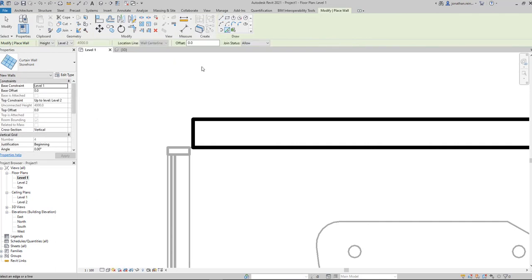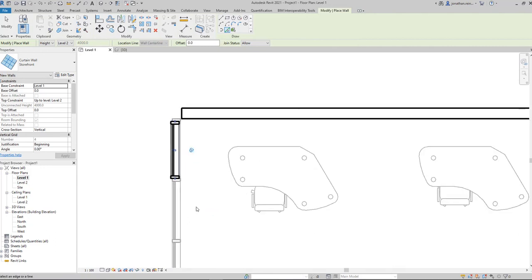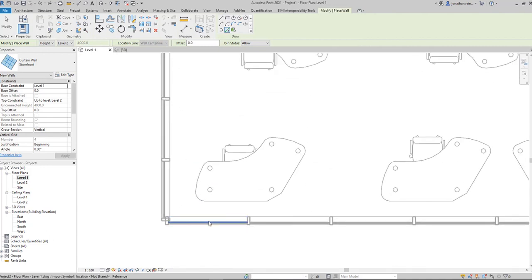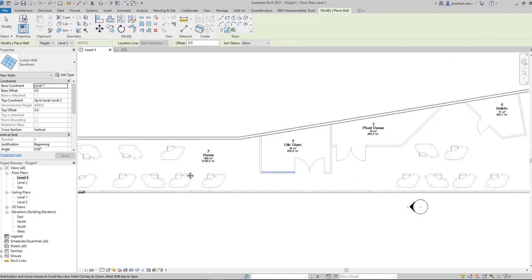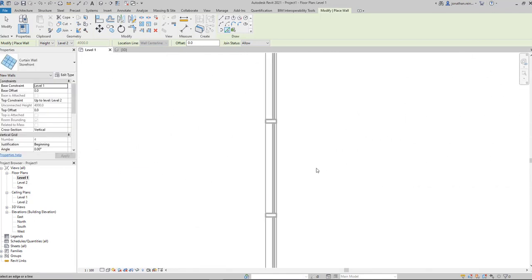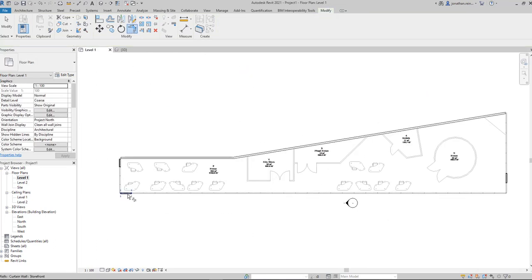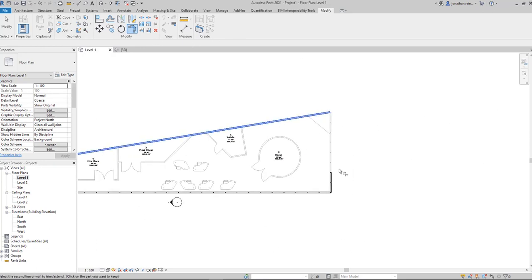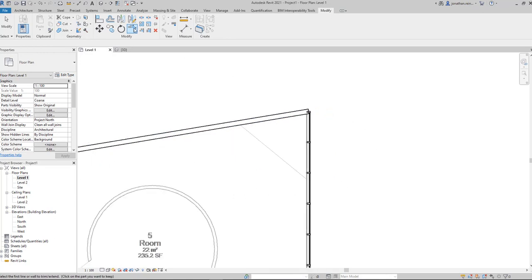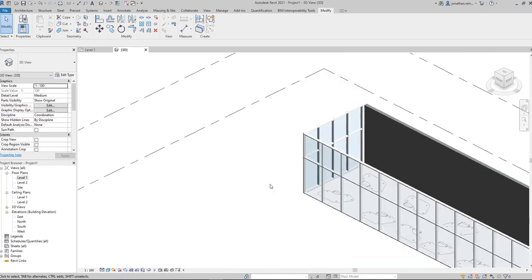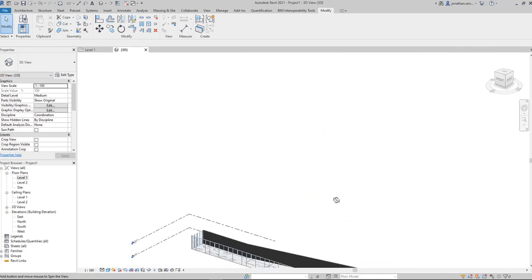I'm just going to pick lines. All I'm going to do is pick one on each facade, and then I'm going to use the trim command just to connect them. Same on this. So what I'm going to do here now is just connect this to that. It'll generate all the way up there, and same to there. And then I can fillet this one here, or TR, the trim command up here, similar to your fillet command in AutoCAD. And you can see that's generated a floor plan within that as well.